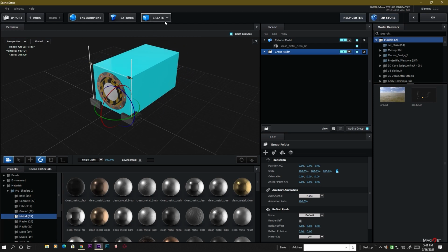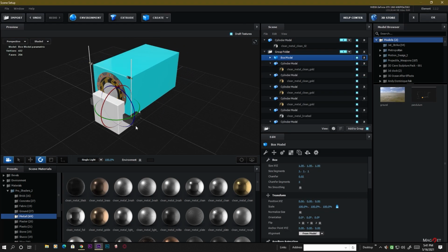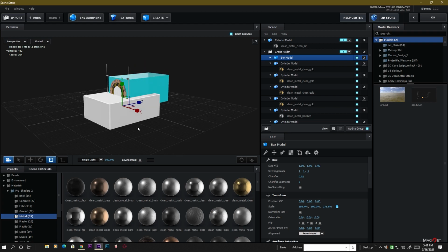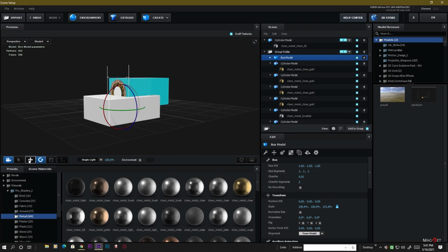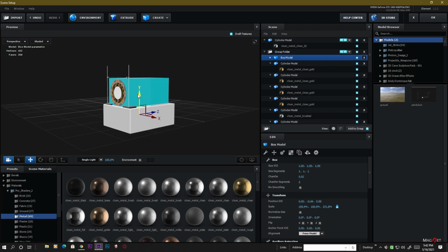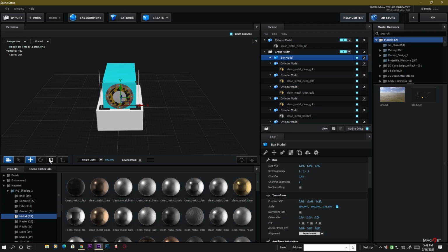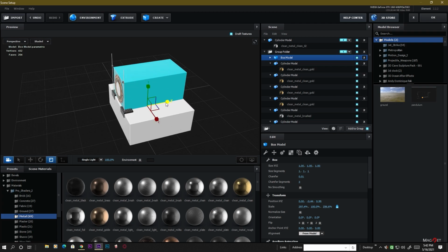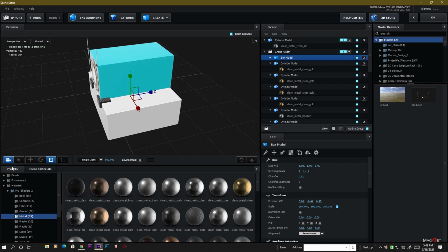And also we make some basement here, so create a solid here, I mean this box primitive here, and we go to the scale and increase the scale. First we place it here in the bottom part like this, and we also increase the size, and also we decrease the chamferness. Okay, and then we also duplicate this.